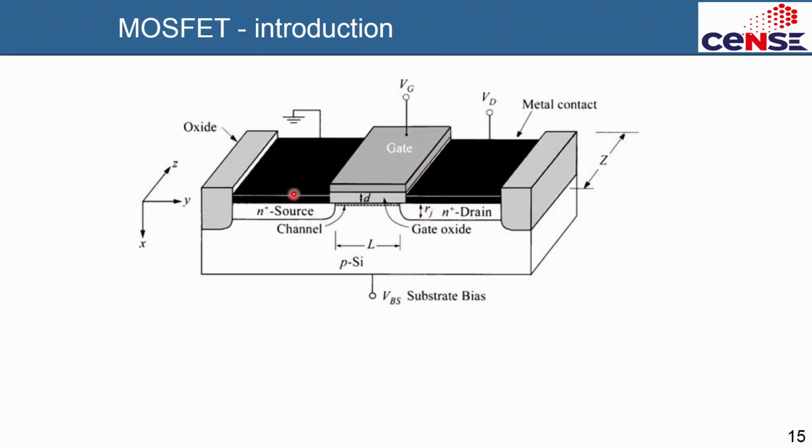So what you do is that this source you ground, which means you apply zero potential, and on the drain you can apply a higher voltage like plus 2 volt, plus 5 volt, plus 10 volt, whatever. So that when you apply a voltage difference between this point, the drain, say plus 5 volt, and ground that is 0 volt, in between them there is this channel that is a high density of electrons that is formed because your gate is now biased at threshold voltage or more.